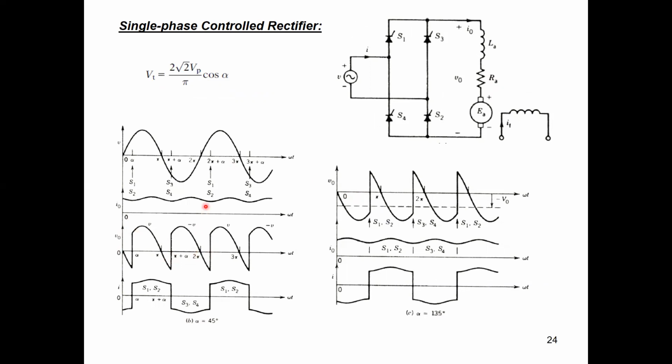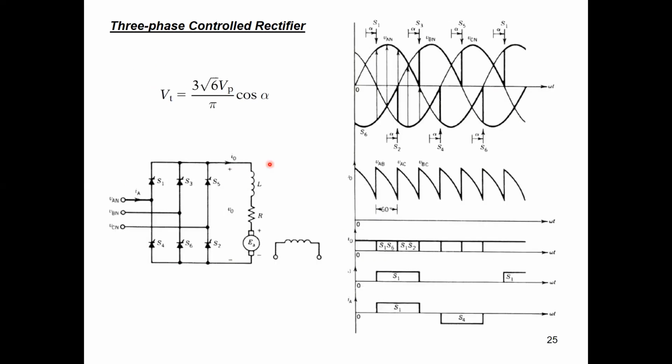So we have a higher voltage for the 3-phase, and also the voltage ripples are small, and this can be smoothed using a small capacitor if required. But to be honest, for DC drive applications, we don't need filtering, because the machine itself will filter the voltage and current.